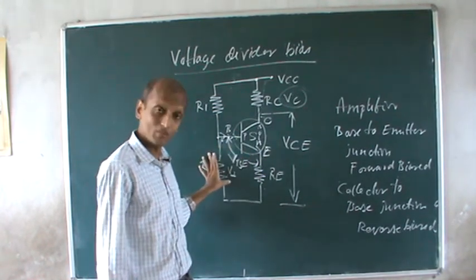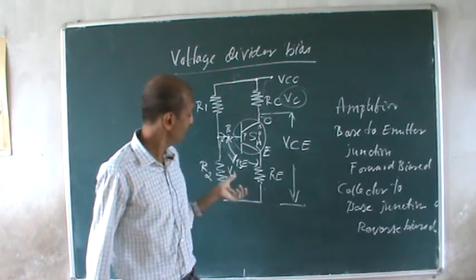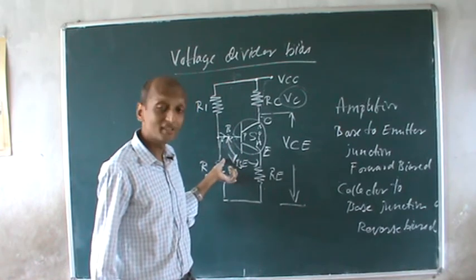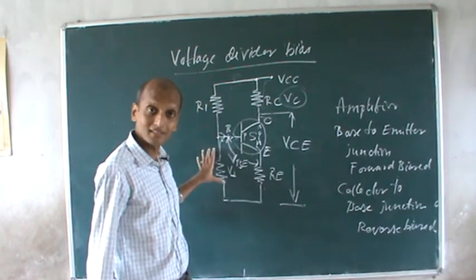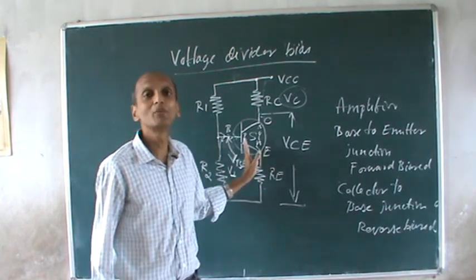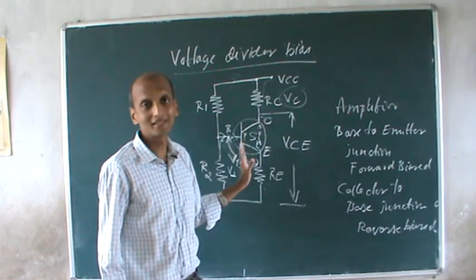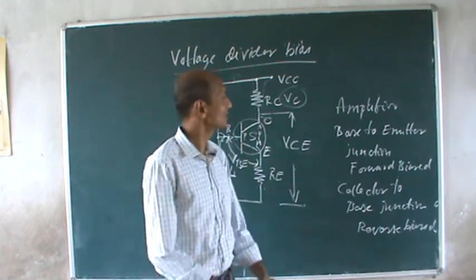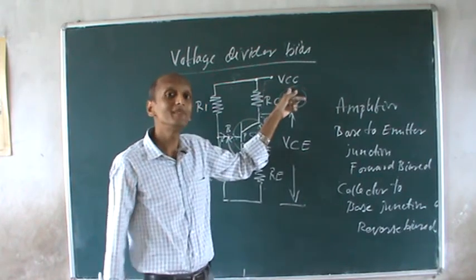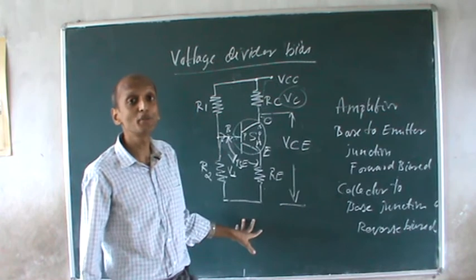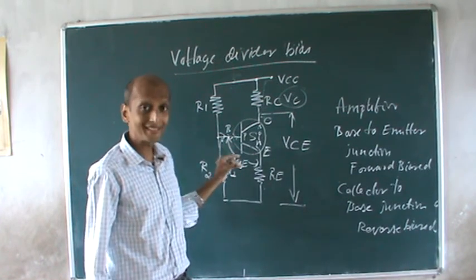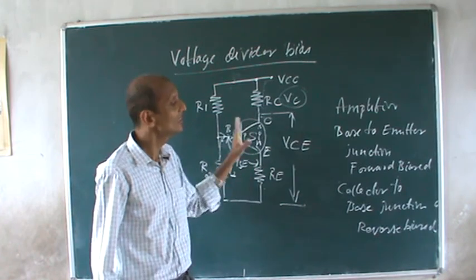Okay, so what amount of voltage do you need across your input terminal, or VBE? I should select the resistors so that they will make so and so voltage drop, and that voltage will be provided to the transistor input and output terminals. So likewise, we have this voltage divider bias, which makes use of only one bias voltage, and this is also called universal bias. This is a very widely used bias technique, and it is used in all of the circuits.